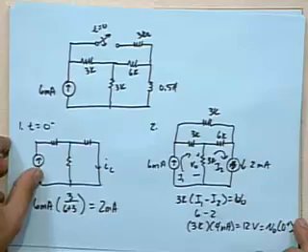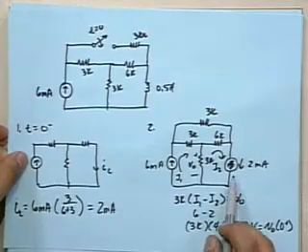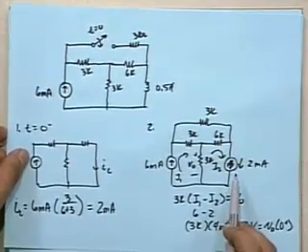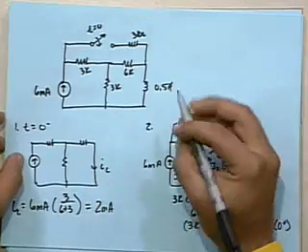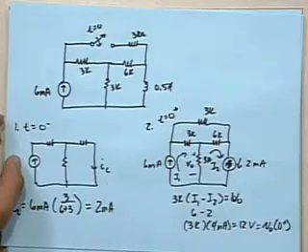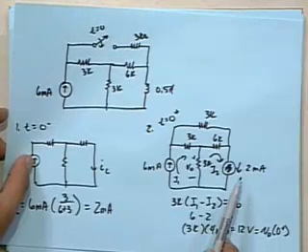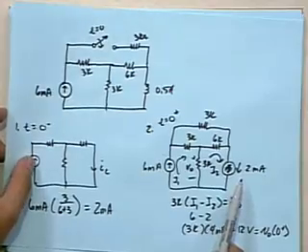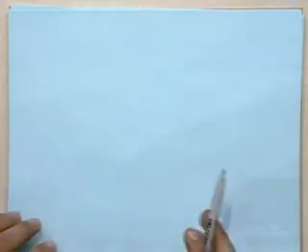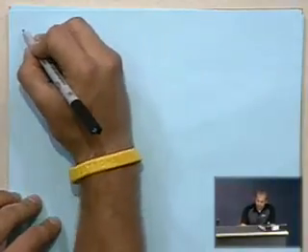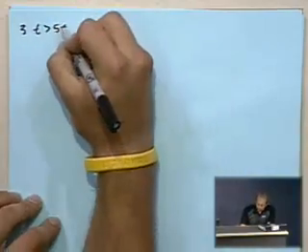One of the things I did see on a couple of quizzes was what happens to the inductor. People would properly solve for I sub L here, but then when they looked at the circuit at time greater than 5 tau, they would replace this inductor with an open circuit for some reason, and that would screw up their analysis. Under steady state DC conditions, the inductor acts as a short circuit. So, 5 tau.